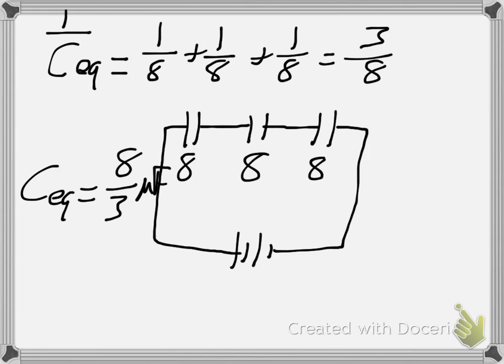Alright, so just a little bit over 2 microfarads. So that is how you get the reduced circuit. Now, recall to solve part B, well, I guess we did just solve part A, didn't we? To solve part B, the charge on each capacitor, label this as C1, label that as C2, and label that as C3.